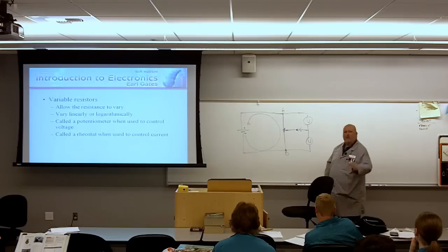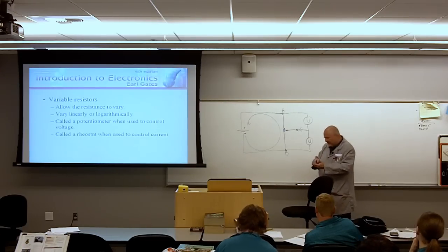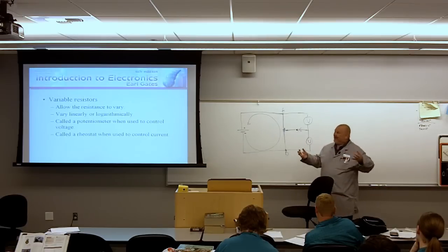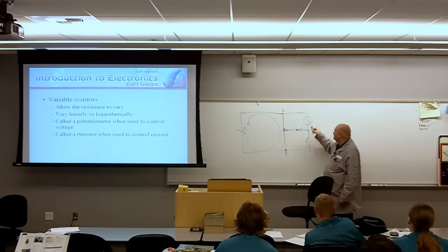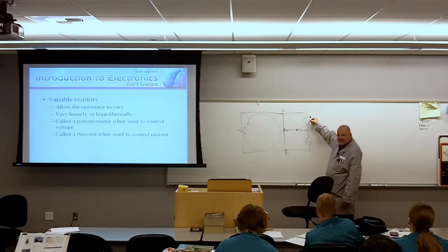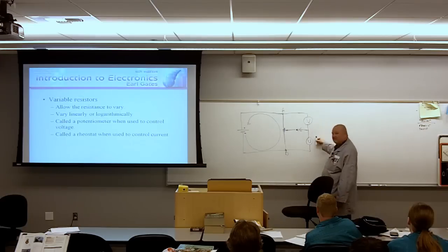I like you. You're keeping it basic. Half. That's the way I want you to keep it. I ask that question, I see somebody going for their calculator. It's like, I haven't given you any numbers. You can't calculate this one. If I've got it set smack dab in the middle, I'm going to get half my voltage here, which means I'm going to get my other half voltage down the bottom. So if this is 10 volts, I get 5 volts here and 5 volts here.